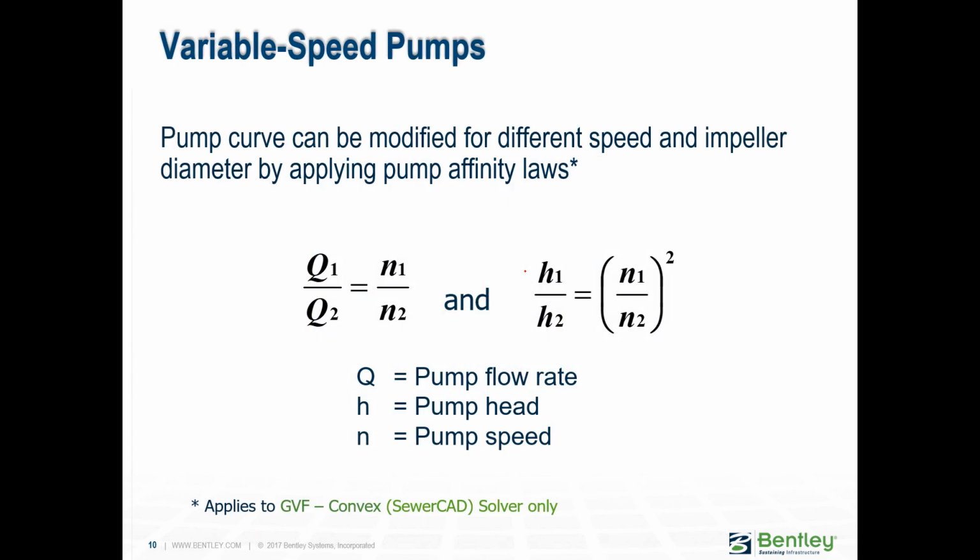So that's for a typical centrifugal pump. But nowadays there are a lot of these variable speed pumps. The difference is that with a centrifugal pump, when it's on, if the needs of your system change, you can't really alter that pump. It's just always going at the same speed. And if you have a lot of changing conditions, that pump might be too big for certain situations and just okay for others.